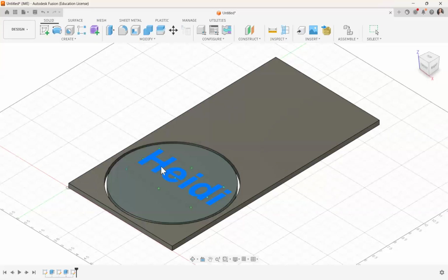You just want to extrude the pieces of your design. Okay? And so I want to cut this. I'm going to choose cut. Okay? And I'm going to, again, select somewhere in my design. I just selected the I, and I'm going to extrude this down. We don't want to extrude it up because, again, that's creating material. We want to cut material away.